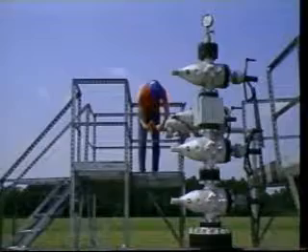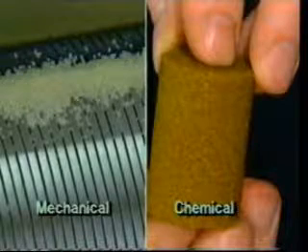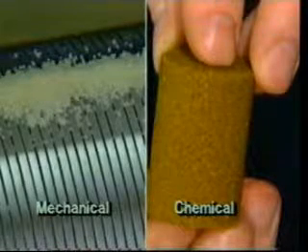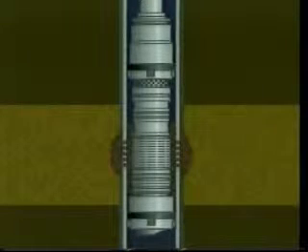The production of formation sand has proven to be a serious problem. It can result in unacceptable reductions in rates and damage to the surface and downhole equipment. Sand control measures may include restricting production, optimizing perforating techniques, and using mechanical or chemical methods to create a highly permeable downhole filter. One common sand control method is the gravel pack.